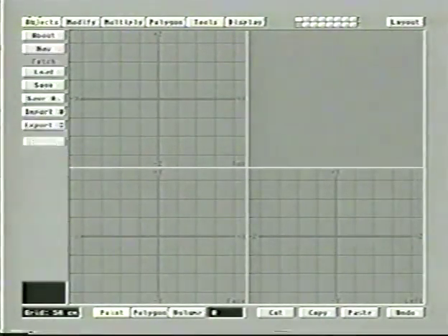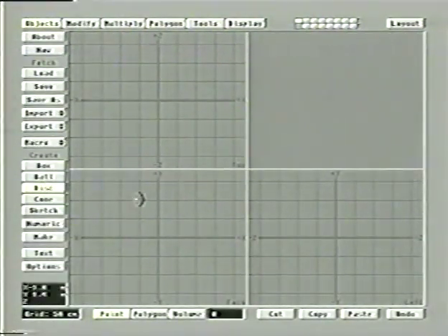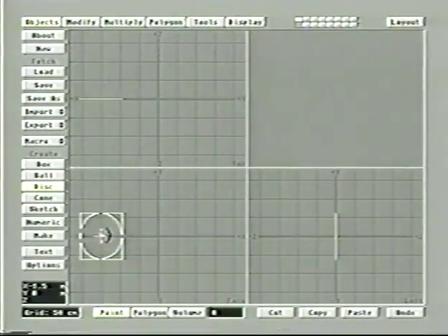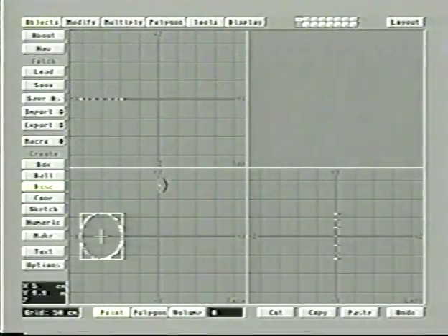And let's start by just creating a regular disk object. And I am offsetting this disk object from the center point. Now, what lathe will do is instead of pushing this object back into the distance, lathe will actually sweep it around a center point. And we set that center point when we select the lathe tool. And by sweeping it around, it's actually going to give it, again, 3 dimensions.